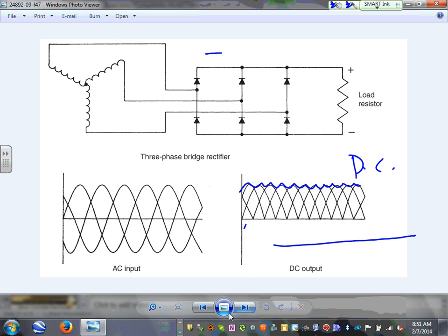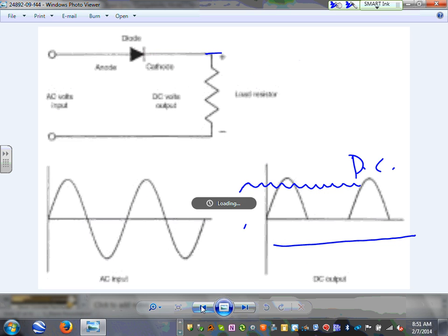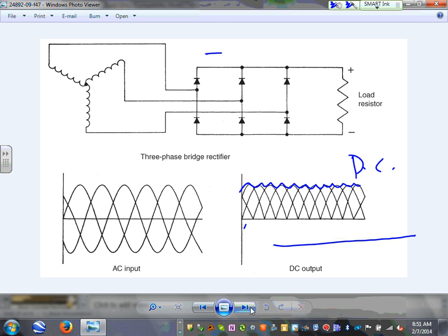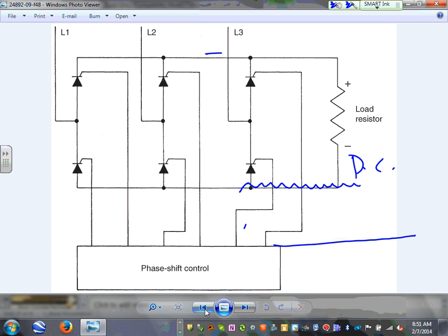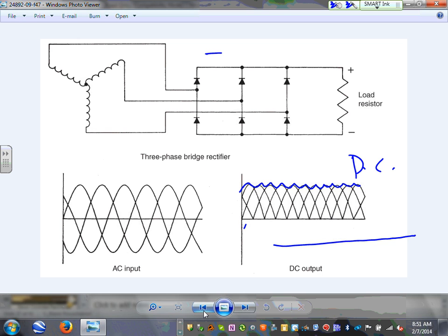All you have to know is that typically all of them are full wave rectification now, single phase or three phase. By doing it this way, they can get you a source of DC from an AC. So if you have a DC motor in a machine in a building, you need to power it. What do you need to ask for? You need to ask for a DC drive. What is a DC drive? It takes the AC 480, for example, and converts it into a DC, let's say 400 volts. That's it. How does it do that? It takes multiple diodes, semiconductors, like right inside your laptop, and allows the current to move in one direction, not the other, and converts it into a DC.